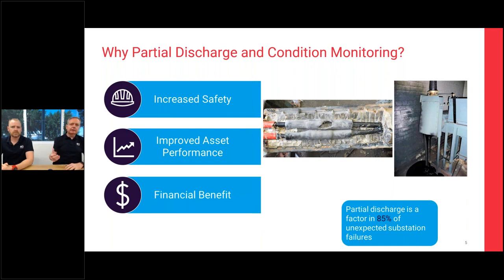When we're talking about the terminations in the switchgear and the substations, the safety aspect can become significant. You can see the picture on the right, in this particular slide, of an old compound insulated cable box which has exploded. If we're in the substation at that time, then obviously we've got a safety aspect. The picture in the middle is of a joint that has failed. If that fails, it's directly buried, underground, so we're not realistically going to get much of a safety impact. We're going to get more of a network performance impact.